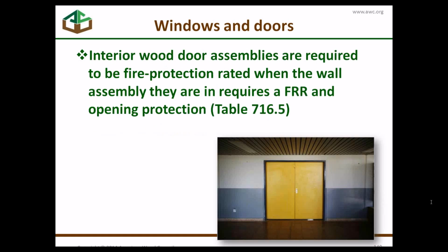What about interior doors? When do they have to be something special? You can have wood interior doors. Again, just like exterior walls, it all depends on the wall that they're in. Does the wall have to be rated for some reason? Check table 716.5, and you'll find out if that door itself has to have a fire resistance rating.